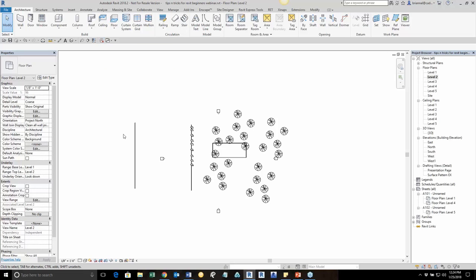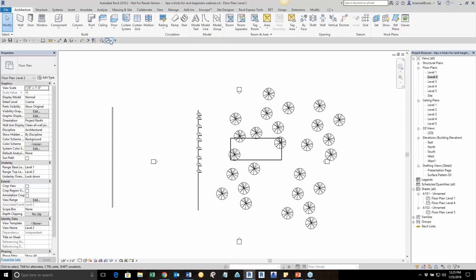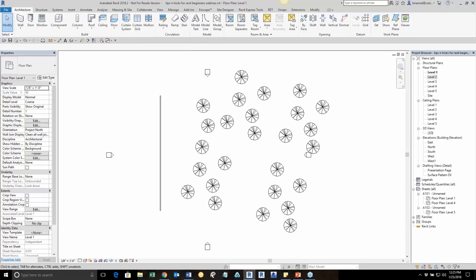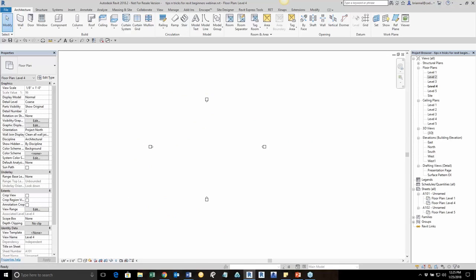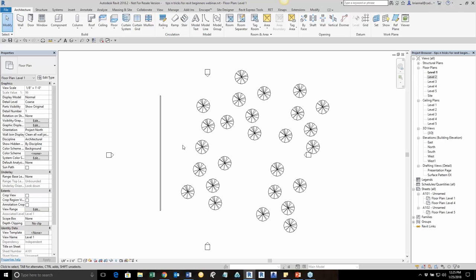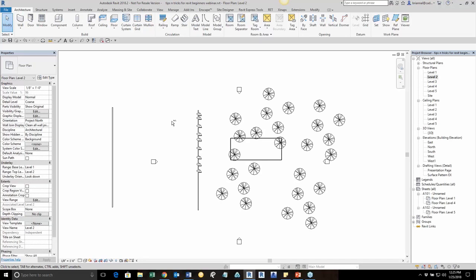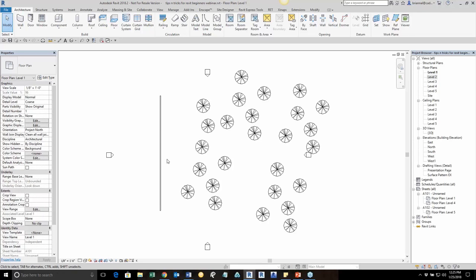You'll notice here I have multiple windows open, and if I needed to go back, or if I wanted to cycle through to see what other views I had without using the drop down here, I can use another keyboard shortcut, Control-Tab, to cycle through my views. So just as much as cycling through forwards, maybe when I have a bunch of these views open, I don't want to have to cycle through 10 of those views every time. So I can do the Control-Shift-Tab to go backwards, which is kind of nice too. Saves me a couple of cycles through that way.